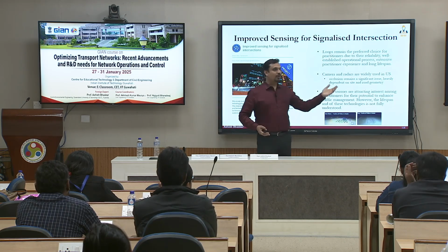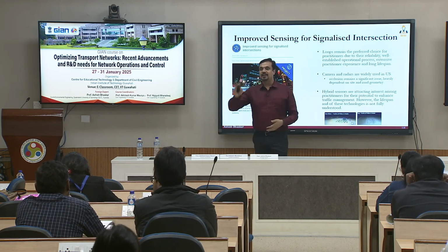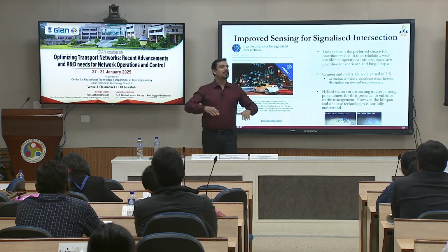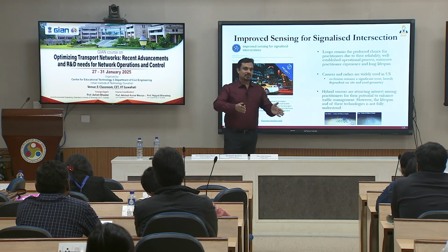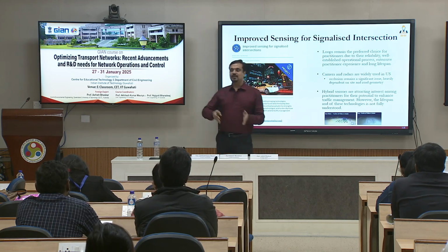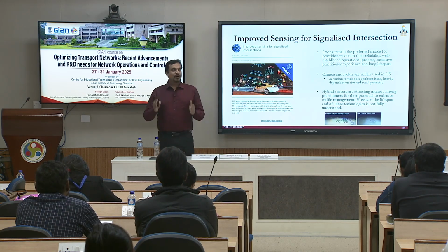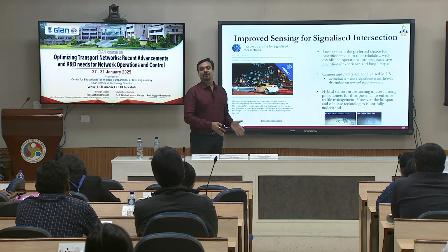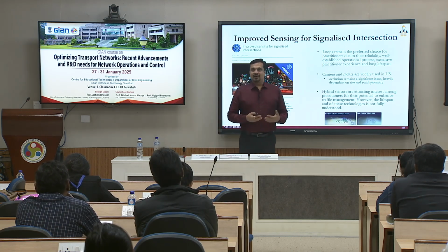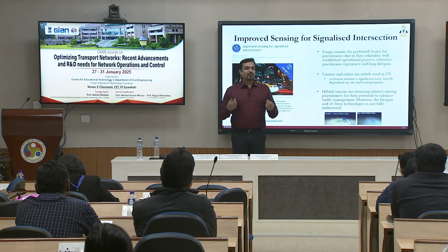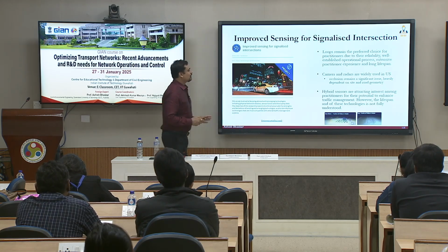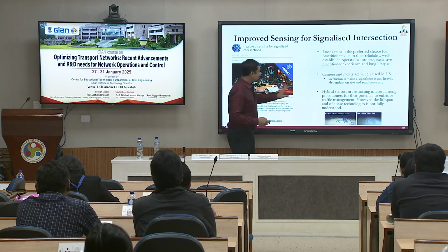You have seen that no matter whatever optimization you do in Sidra or Transyt 7F, or you write your own code, at the end of the day, when you come to the ground reality of implementation, you make your rules and you work accordingly. As long as the system is working fine, because nobody knows what is the optimal solution. That's the thing with traffic signals. As long as people are not complaining, you as an engineer are happy. So they are fine with that one.